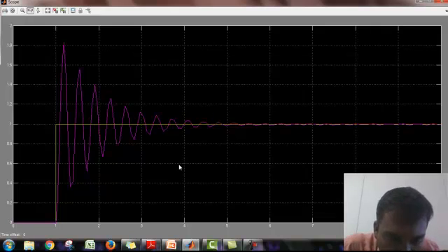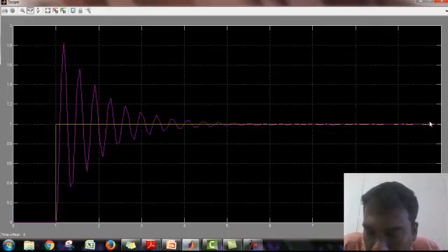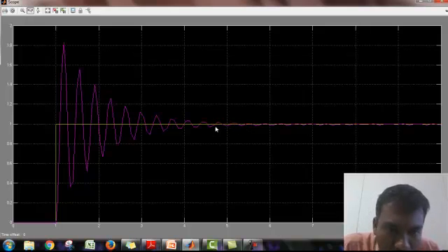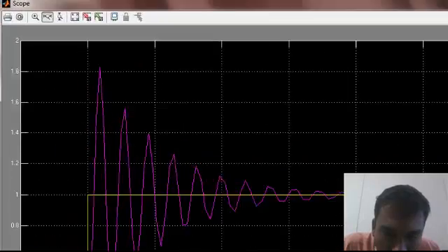So where is the KC value? Here you have some fluctuations, and from this point you can find the stable system. At one stage we get the stability. See, this fluctuation is constant from here. So you have to find KP. For KP value 300 you're getting this, and you have to find the time period. So further you have to zoom the x-axis, starting from here, where you get the standard stability of the system.